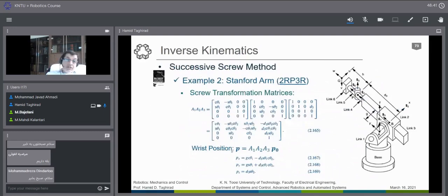So this is very general. We did it several times, as we see. Just summing the square of this equation will reduce the complexity, and you can see from the physical interpretation that the length of this point to here really doesn't change by theta 1 or by theta 2. Only the length is changing by D3. This means that we can simply eliminate theta 1 and theta 2 from this equation, and this elimination is done by summing the squares and using the trigonometric relation in here.